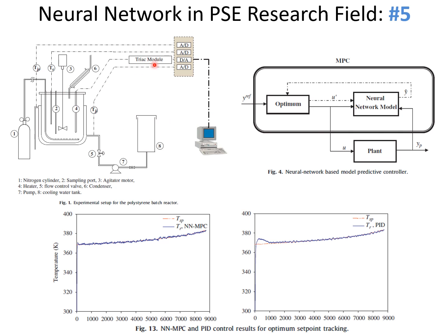The nominal points when you implement online may be slightly different. That is good enough. But if there's a major difference, then that's a big issue. It means the nominal operation and characteristics have changed, and then it may be difficult for the network. That one you may have to retrain again offline and put it back. But if it's close to the actual nominal training, it's okay to add more data and train the neural network. It's not something difficult for an AI system. This is why we call it artificial intelligence. It has an intelligence as long as the training data is good within the operating range and not too far different from what it has been trained on before.